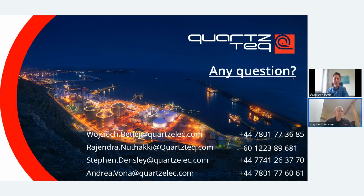Okay, a question here. How often should you check PD on a generator that does not have permanent online monitoring? That's a tricky question, because based on what I just said, we can certainly say that if you do it periodically, it might not work. And I just gave you an example of a situation where it didn't work. Having said that, the standard industry practice for offline PD is to perform annual testing.